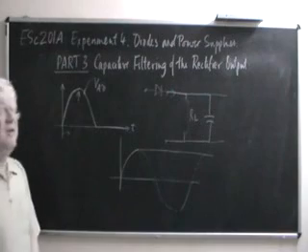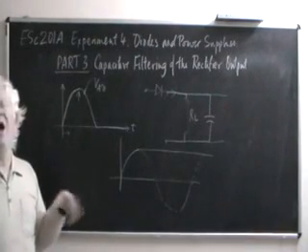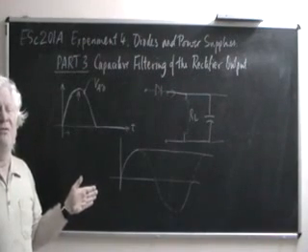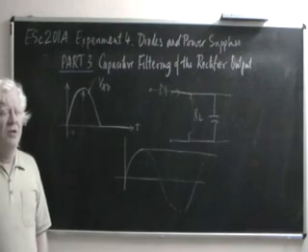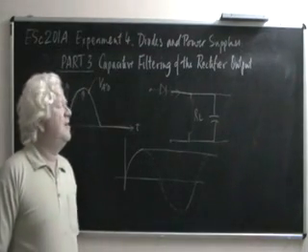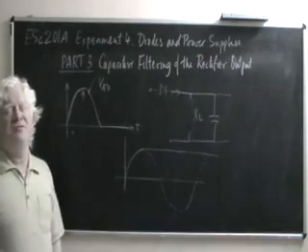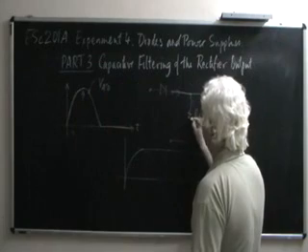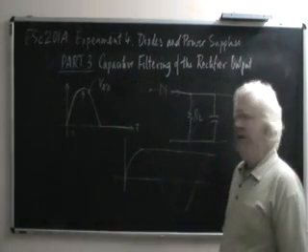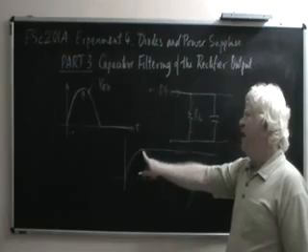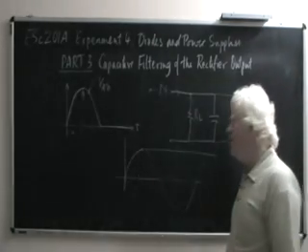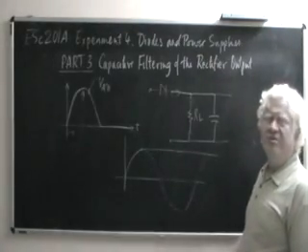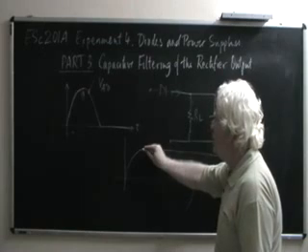However, if we have any kind of resistance across which the capacitor can discharge, then a very different thing happens. If there is any scope for the capacitor to discharge, such as by having a load resistance, let's reintroduce it over here. Then after this point, the capacitor does indeed begin to discharge, and instead of its voltage remaining constant for the rest of the future, it starts drooping.